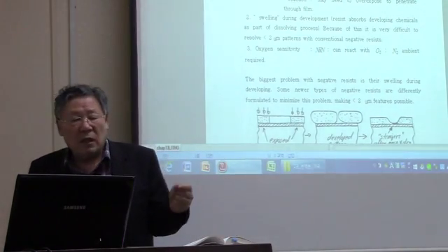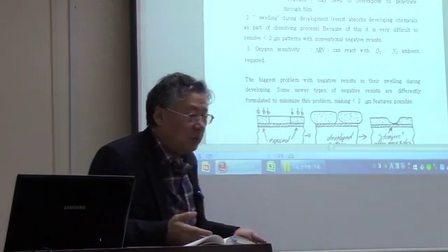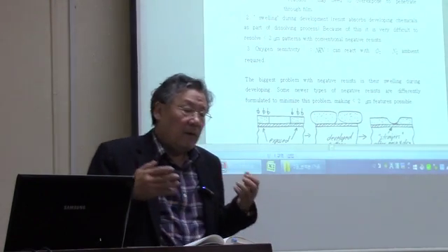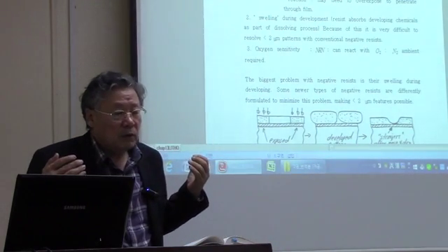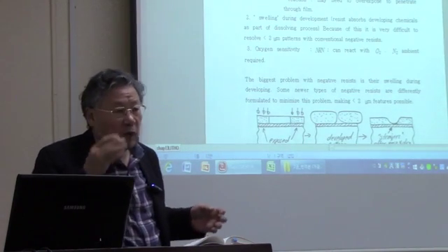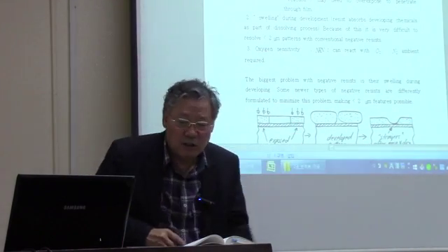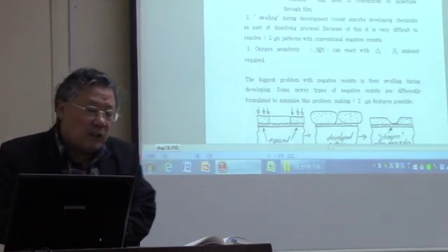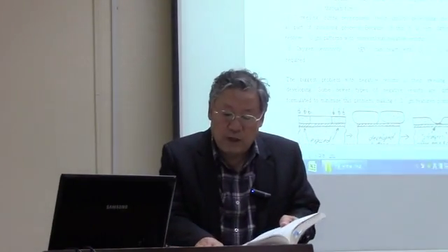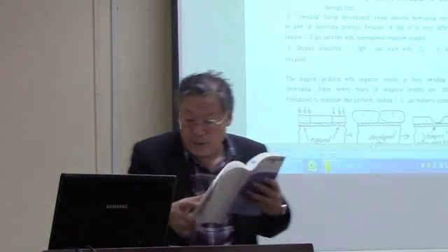By the same token, the negative photoresist is cheap and has a good throughput, but people try to use the positive photoresist because they do not want to sacrifice the resolution because of these disadvantages. Okay, on Wednesday, we're going to talk about the positive photoresist. We're just going to pick up from here. Okay.